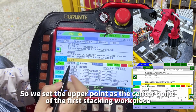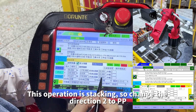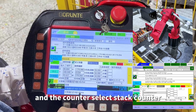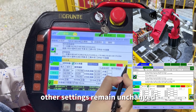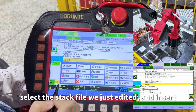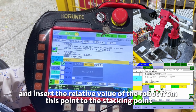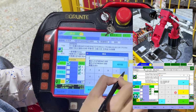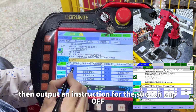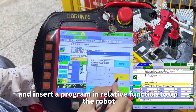So we set the upper point as the center point of the first stacking workpiece. Click Insert. This operation is stacking, so change the direction to 2 PP. And the counter, select Stack Counter. Other settings remain unchanged. Tick use stack, select the stack file we just edited and insert. And insert the relative value of the robot from this point to the stacking point. Then output an instruction for the suction cup OFF and insert a program in relative function to move the robot up.